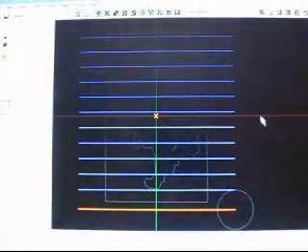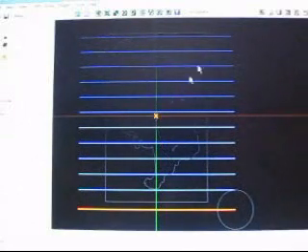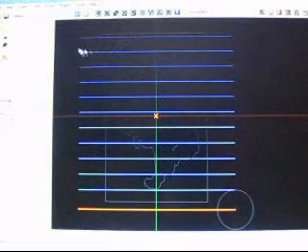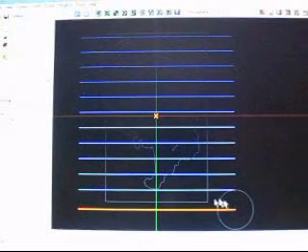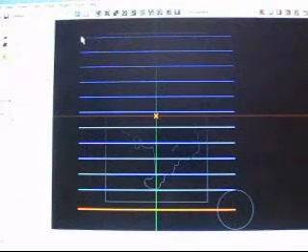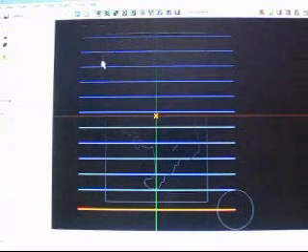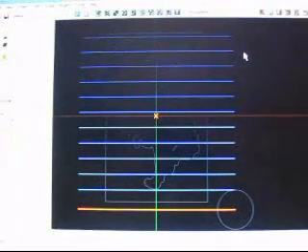Okay, so what it's going to basically do is go from my home position out to here, and then it's going to conventionally cut, then come back to the next line and conventionally cut in this direction, the same direction that you drew your line in. In this case I drew it from right to left. Now if I had drawn it from left to right, it would be climb milling. It would come up here and it would cut in this direction from left to right, and then come back and then cut again from left to right.